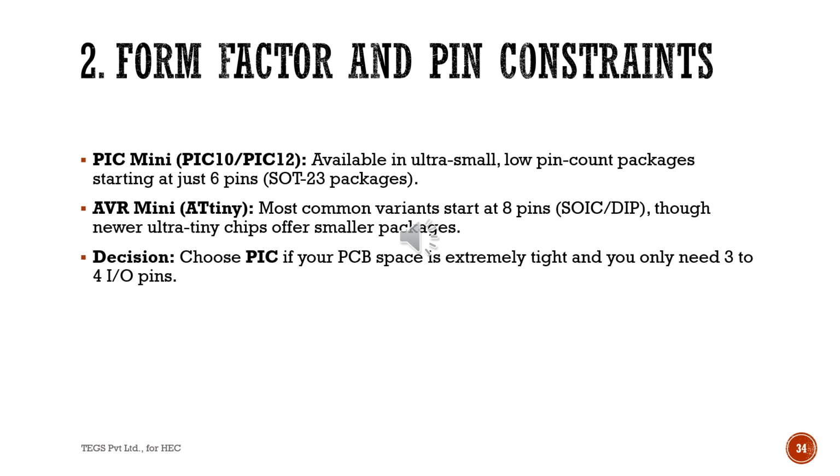Second criteria, form factor and pin constraint. PIC Mini, PIC10 and PIC12 are available in ultra small low pin count packages starting from just 6 pins. AVR ATtiny, most common variants start at 8 pins, though newer ultra tiny chips offer smaller packages. Decision: choose PIC if your PCB space is extremely tight and you only need 3 or 4 I/O pins.